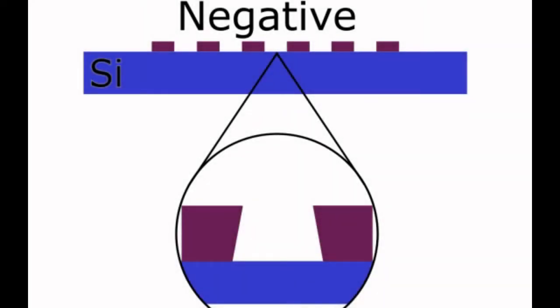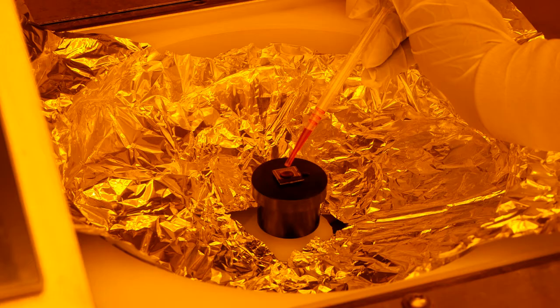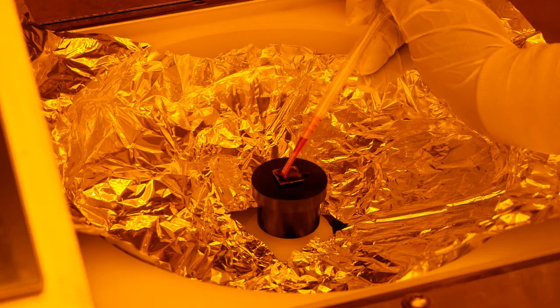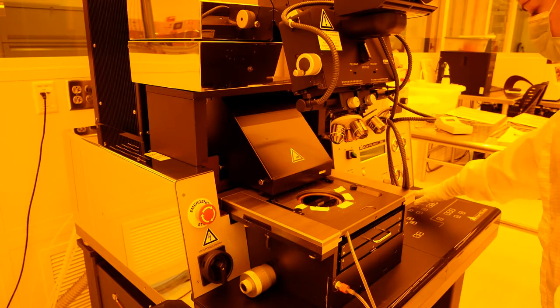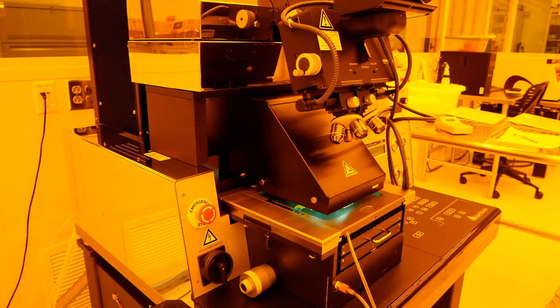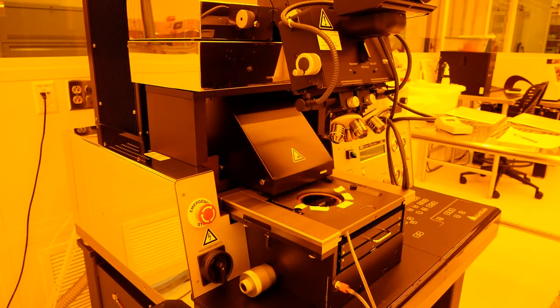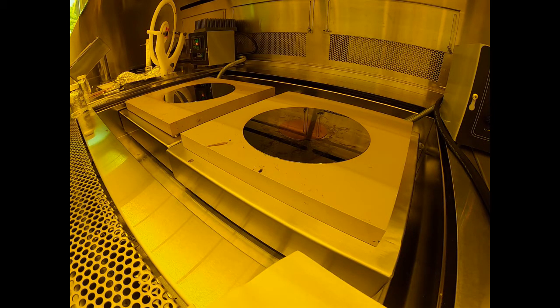Now that we have our graphene layer, we need to add source and drain electrodes. To do this, we will pattern a chrome gold layer using a liftoff process. The first step in this process is photolithography. We spin coat a negative photoresist on the sample, bake it to remove the excess solvent, place it into the mask aligner under a photomask, then expose it to UV light. A second post-bake provides the thermal energy for the negative photoresist to finish cross-linking.